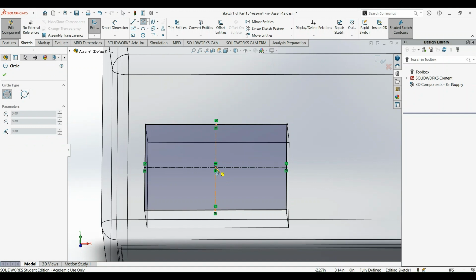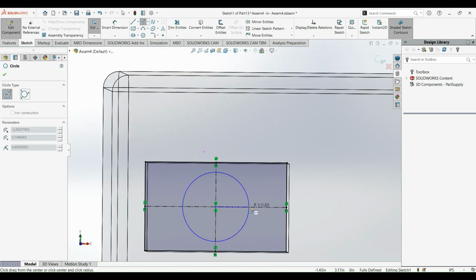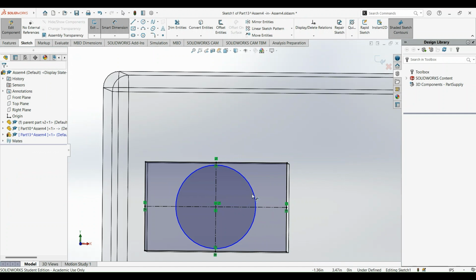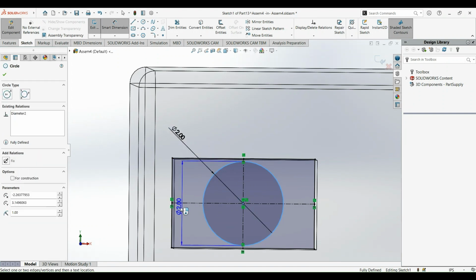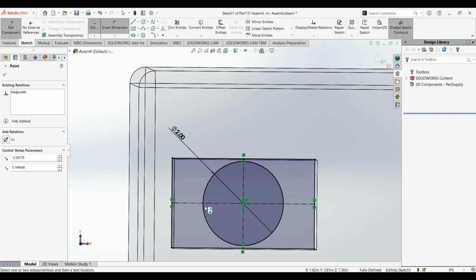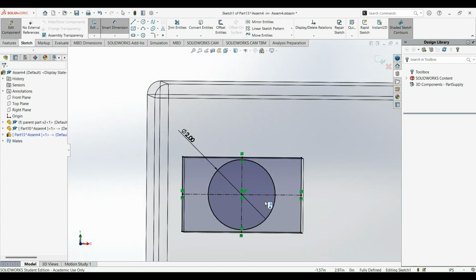I then use some reference geometry to create a sketch of a circle in the middle of the surface I'm using, and then I extrude the circle, and then I again use the circle tool and create another circle on the extruded circle, and then I extrude that circle again, giving me the shape of a protruding lens from the body.